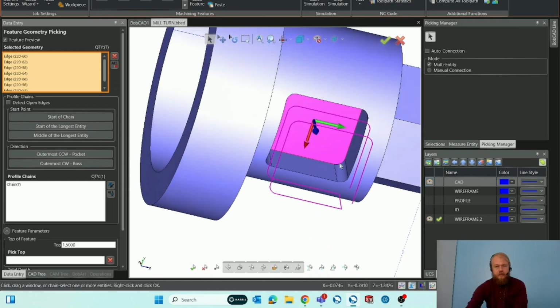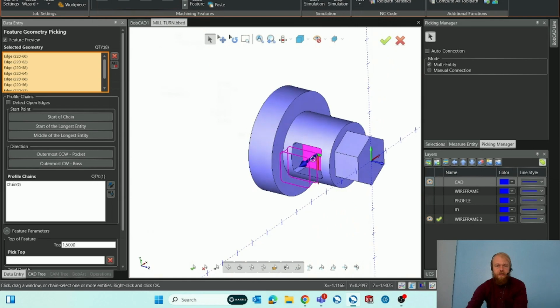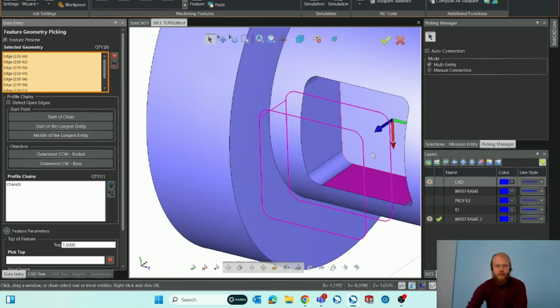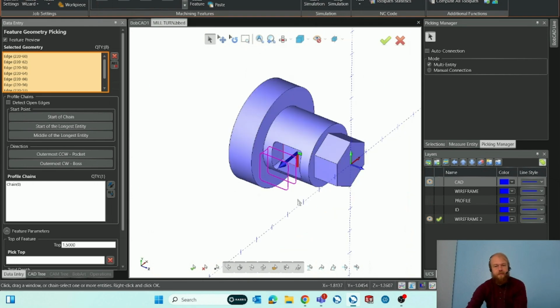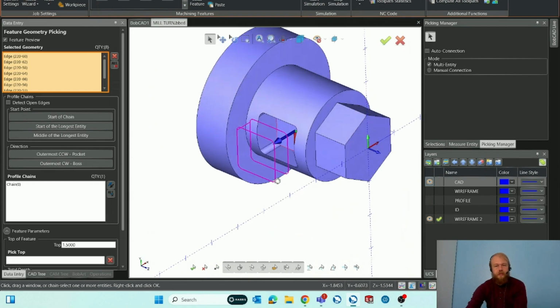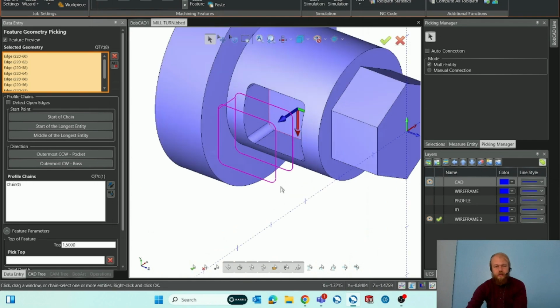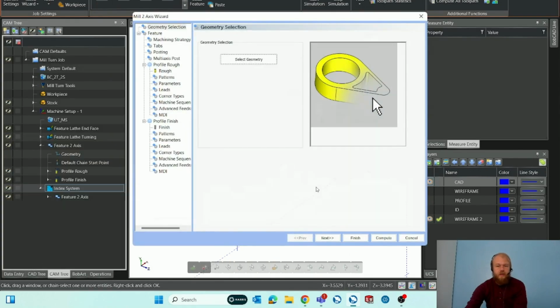Basically, all I did to create this pocket, very easy, just created a square somewhere like right around here with a 1/4 inch radius around the corners and did an extrude cut. Very simple stuff for this 3D model to try to get you guys to follow along there. So I select the edges of the pocket, click OK.